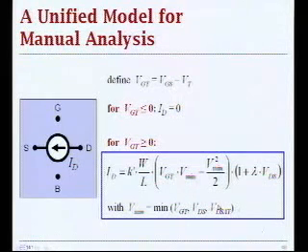If you plug in VDSat, you have your velocity saturated device. If you plug in your VDS, then you have the linear region. So it nicely calculates the I versus V relationship for all possible regions of operation using these simple definitions.